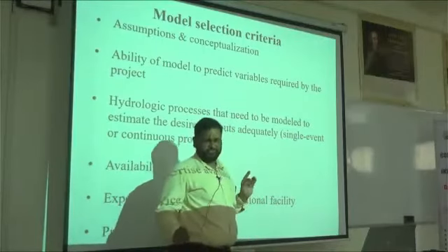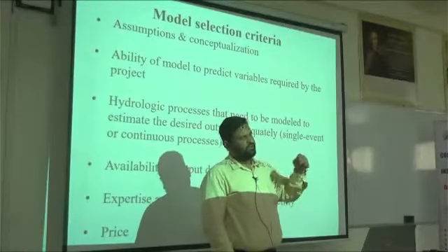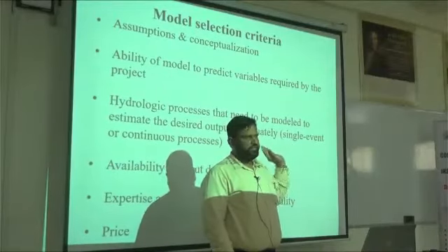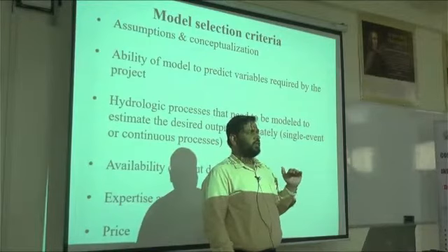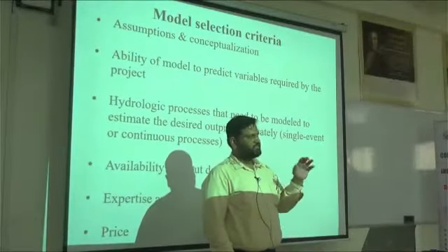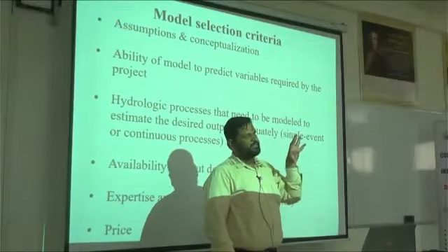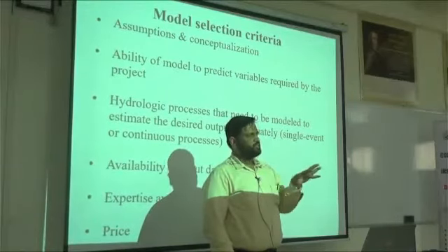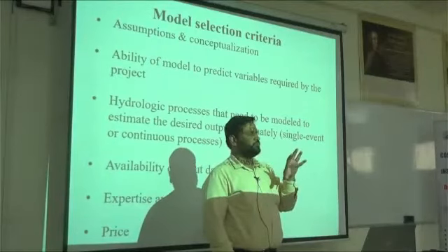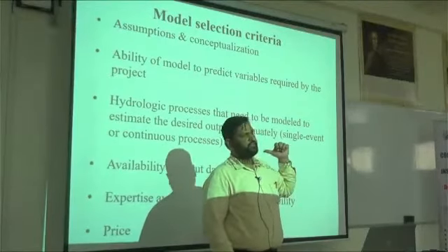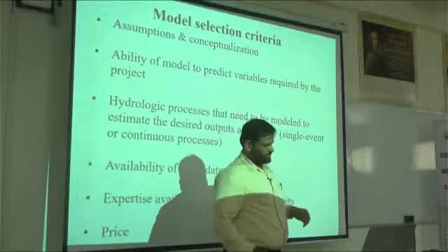And then why are we using SWAT? Because HEC-RAS, Mike SHE, all these are event-based models, or they are generating some kind of runoff. But the advantage of the SWAT model is that it is based on your management practices also. You can incorporate different types of management practices which are taking place in your particular catchment area, like what irrigation and cropping patterns you are using, and what types of land management practices are being used in your catchment area. You can give that input in your SWAT model also. So that is the basic requirement. That depends upon what types of studies you are going to do.